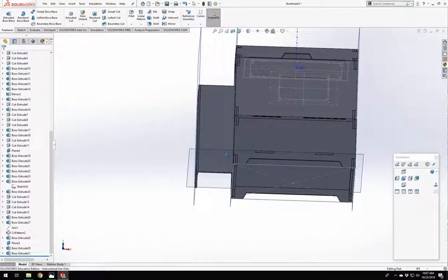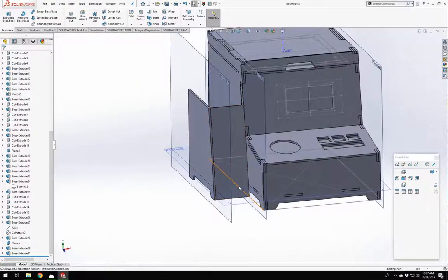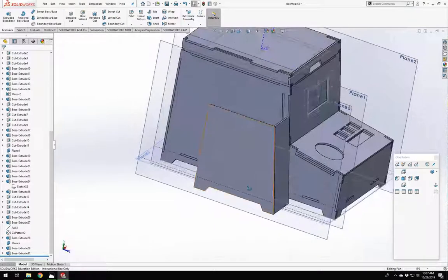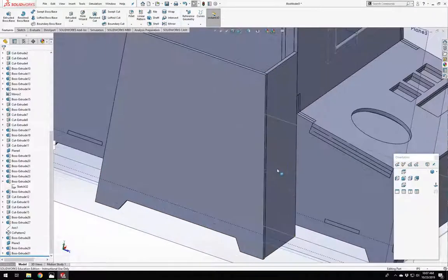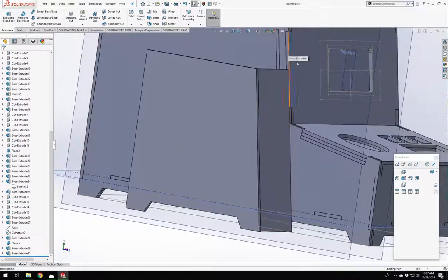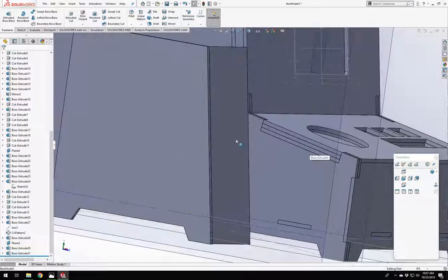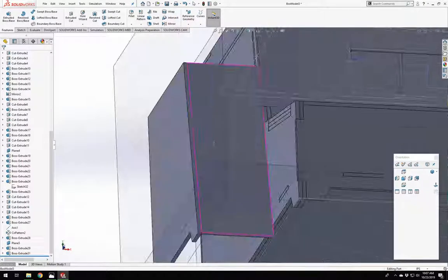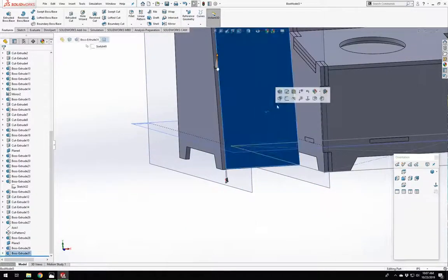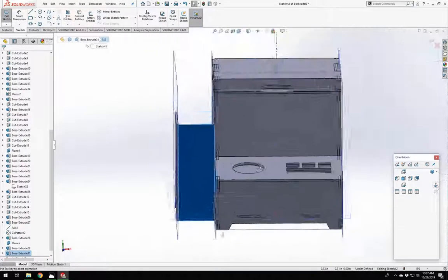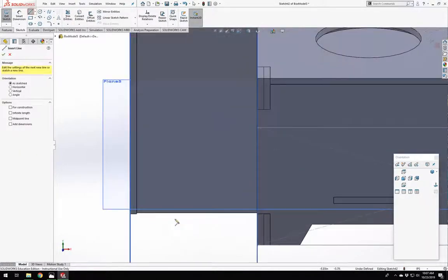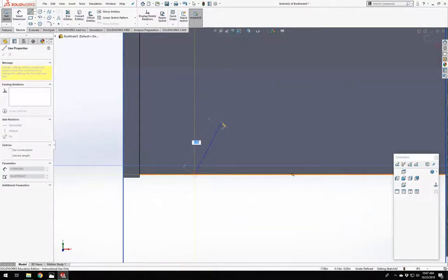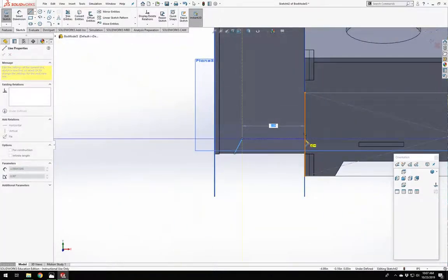One of the critical things with this particular panel is going to be how the bottom foot gets handled and how it gets mounted to this body. Because we already have this finger here and this will be sort of pre-assembled, we're actually going to have it tack in on this lower portion. And we're going to want this foot to sort of match visually. So the way we're going to do that, let's start here and do the foot first. And so we're basically going to do just a cutout like this.